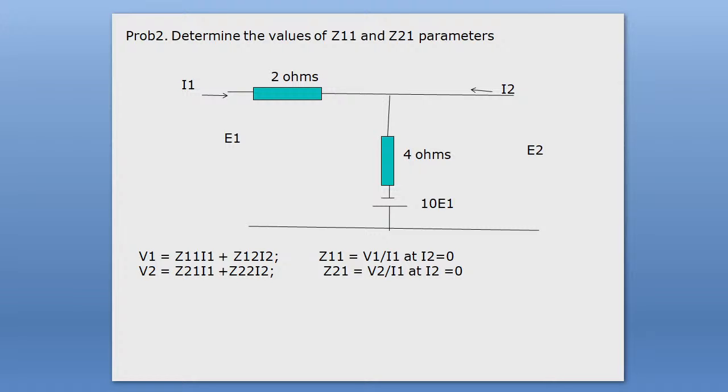Maybe Z parameter, H parameter, ABCD parameter, Y parameter, whatever. You first write the expression of this parameter, then you solve it by considering the KVL for loop 1 and for loop 2, whichever is required for solving the given problem.